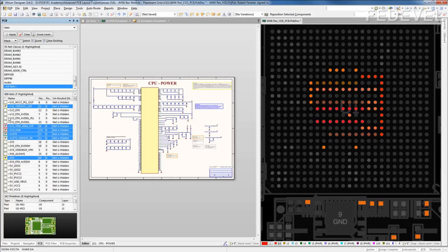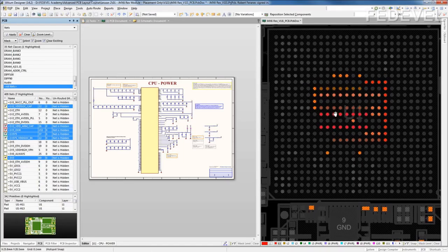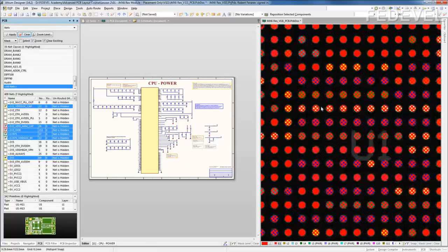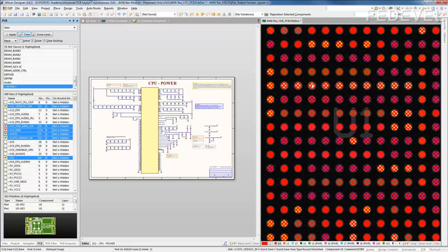The first time I saw it was somewhere in an Intel reference design or AMD design, and since then I use it in every design because it's extremely useful, especially during the layout. You immediately see that you are working with a power net. So I highly recommend putting a plus sign on every power net. Now we can see nicely what paths are connected to power.